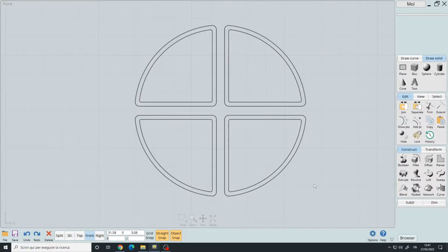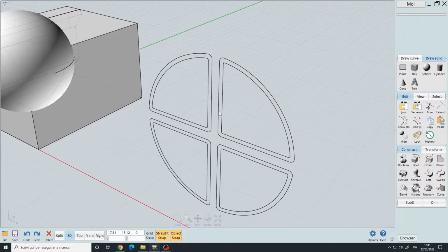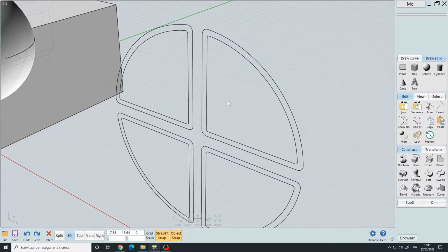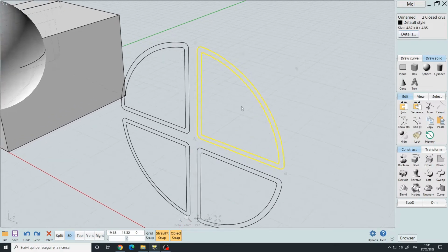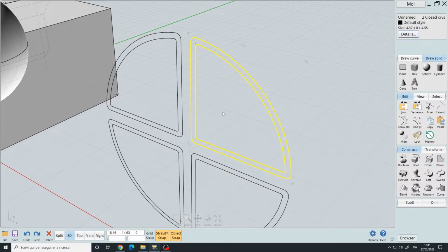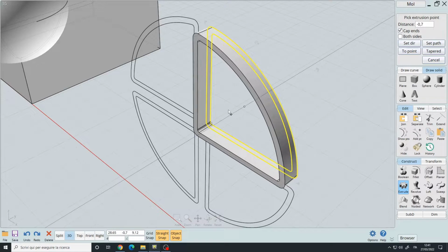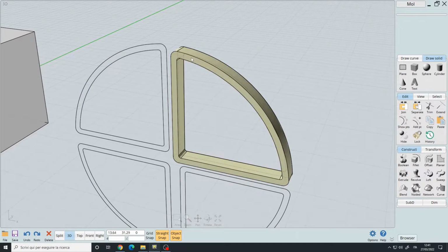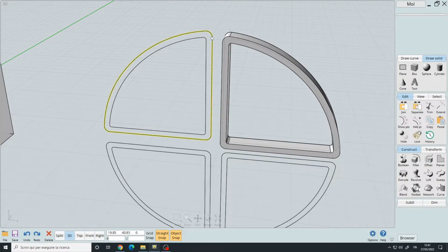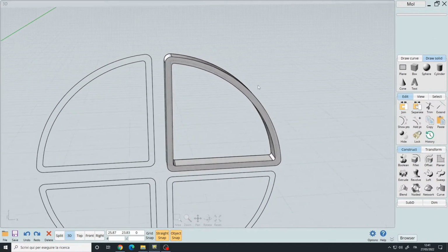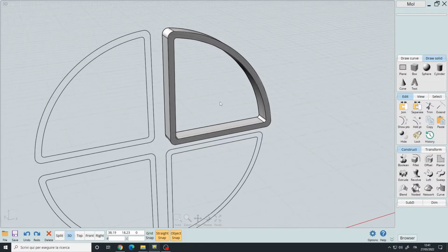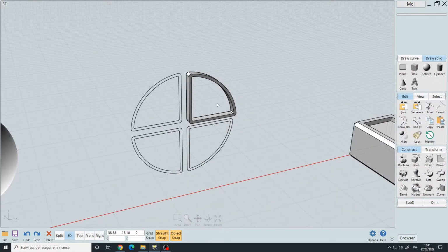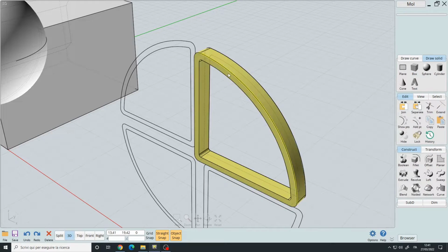Now, one thing to keep in mind when you extrude is that the software will only extrude the inner part between curves. So if I select these two, the center faces will be hollow. I extrude, and as you can see, I only have the space between these two curves that are extruded. All the rest is hollow, so keep this in mind when you work with curves.